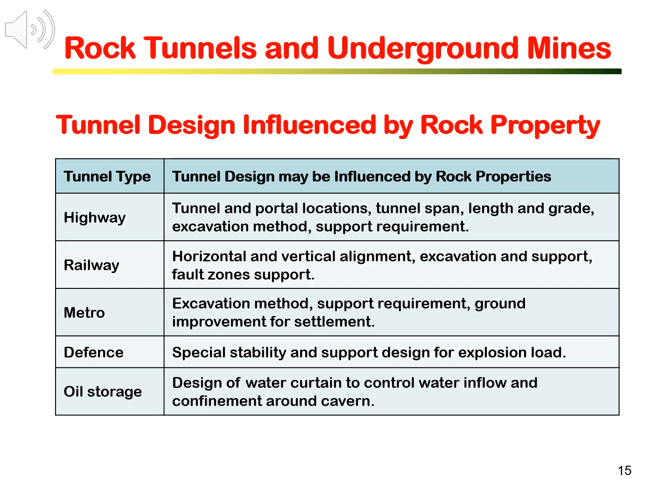Another interesting example is oil storage cavern in rocks. We will need to ensure there is sufficient groundwater confinement around the cavern to prevent oil leakage, and at the same time control groundwater inflow. Therefore, designing and excavating water curtain tunnels above the caverns depends on rock mass permeability, joint connectivity, and groundwater condition.